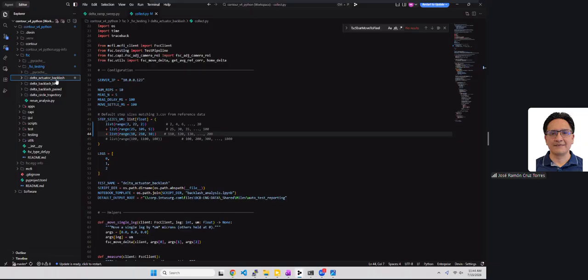And obviously backlash itself contributes to hysteresis significantly. Hysteresis is probably just backlash on the other entities. It is definitely part of that, but it is also tied with the mechanism itself and how much slop there is in backlash, right? Yeah, hysteresis is a good evaluation metric for how an actuator is performing, but it's not as high risk as backlash for our specific uses.